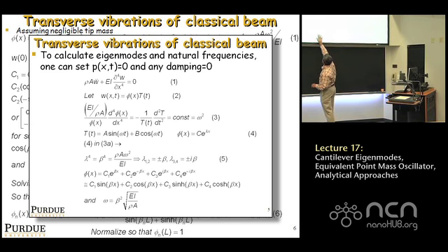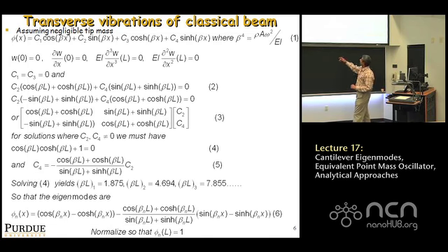Yeah, this is omega. This is not omega squared. Okay? This is omega. So beta squared goes as omega. Okay, so omega is like beta squared. So if you look at the very first beta, it's 1.875. The second beta is 4.694. So if I look at the ratio, 4.6 divided by 1.875, right? That ratio is about between 2 and 3, right?